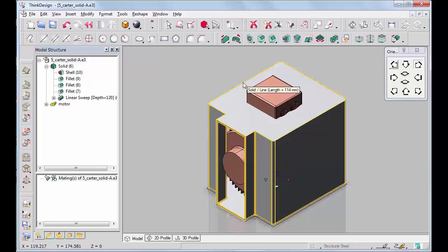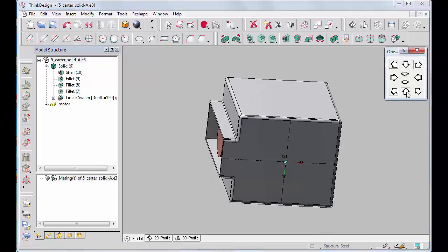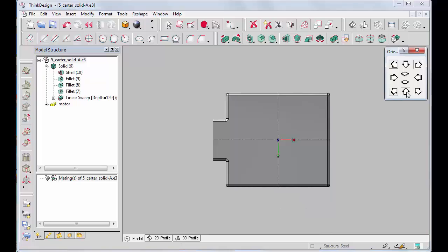At this stage, we need to make the object bendable by creating the necessary rips. We have sharp edges on the top part of the object, while at the bottom we have the fillets with the radii we have previously set. And here are the fillets we were talking about. On such fillets, we can create rips using the face rip command. Let us then select the set of fillets, obviously skipping the one on the right hand part of the object, which are then removed, leaving some openings, as we shall see.